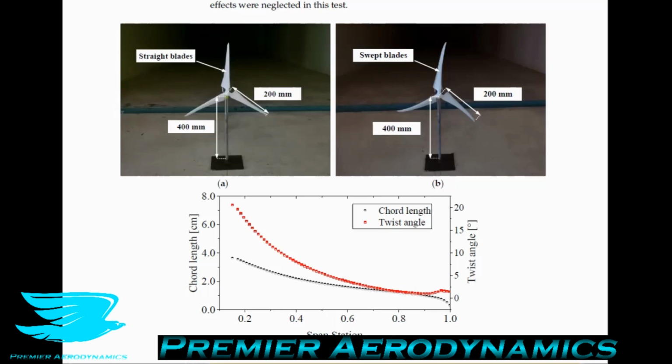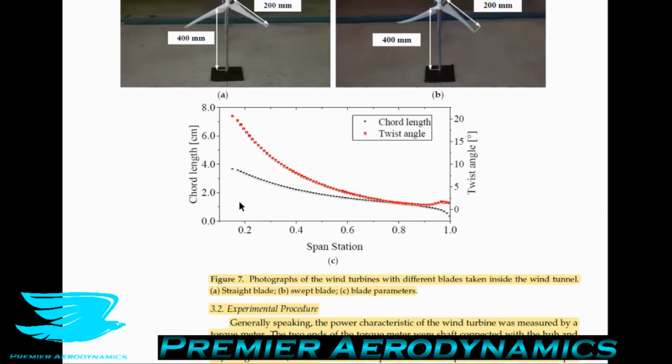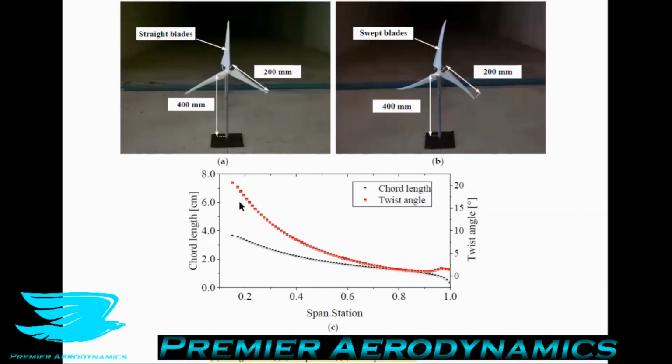Often blockage ratios are around 3%, 5% people would usually run at. So to get 1.4% is really nice. And that means that there's going to be almost no blockage effects or anything else like streamline curvature, for example. These are all parameters that can severely affect the performance of your setup and the validity of the setup. So in here, they have a very nice setup.